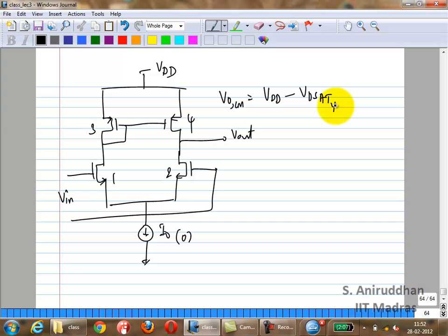In reality, if everything is perfectly matched, you would probably expect it to be somewhere, as we said, VDD minus VSG3. You would expect it probably just based on symmetry. If nothing else, that's it. But in reality, you have to realize that the output common mode is not set well at all. Right? Because